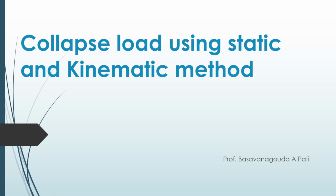So the question: determine the value of collapse load for the proper cantilever beam subjected to a concentrated point load. So this is the proper cantilever member. Proper cantilever in the sense, one end is fixed, the further end is simply supported. This fixed end is named A, and the further end is named B. This member AB is subjected to a point load of magnitude W. This point is named C.